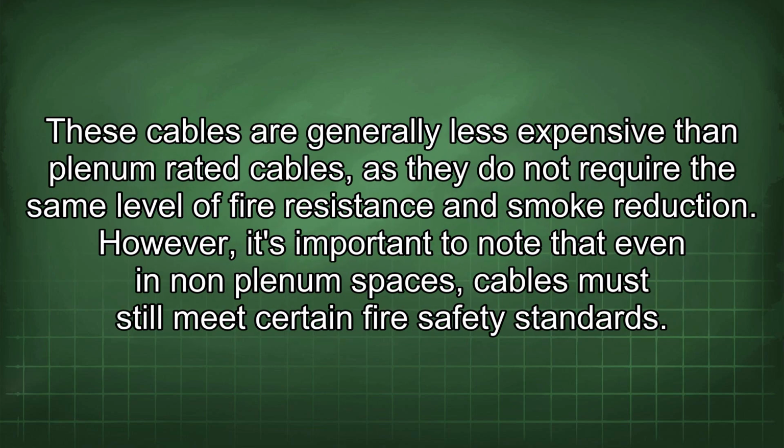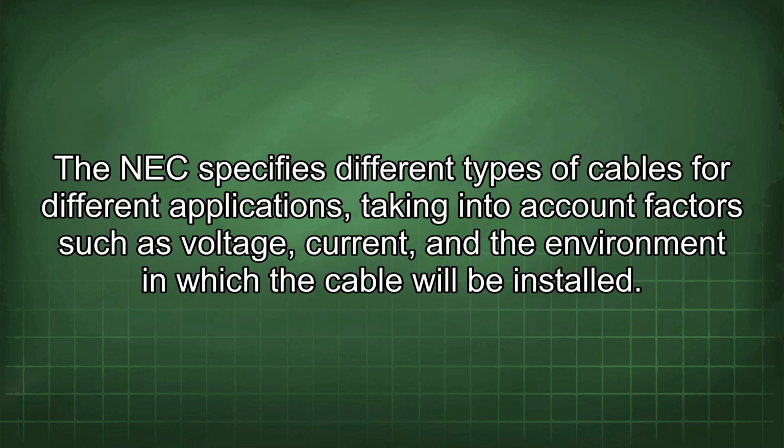These cables are generally less expensive than plenum-rated cables as they do not require the same level of fire resistance and smoke reduction. However, it's important to note that even in non-plenum spaces, cables must still meet certain fire safety standards. The NEC specifies different types of cables for different applications, taking into account factors such as voltage, current, and the environment in which the cable will be installed.